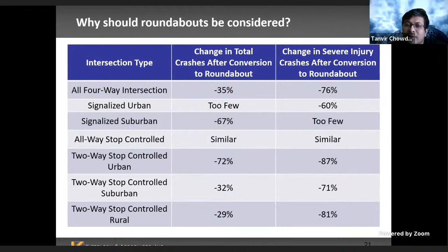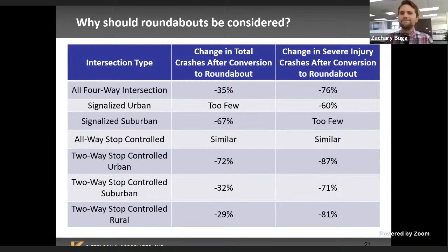Yeah, I think so. That's the way we usually proceed. But suppose after 10 to 15 years, we have a plan to build this intersection as one of the major intersections. But currently we are allowing lots of development around that intersection. If you think about some developing countries' context, in those areas, land acquisition and land management is one of the crucial issues. So for that purpose, sometimes we apply a roundabout to accommodate the land.